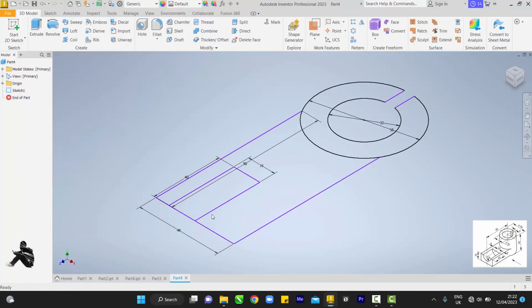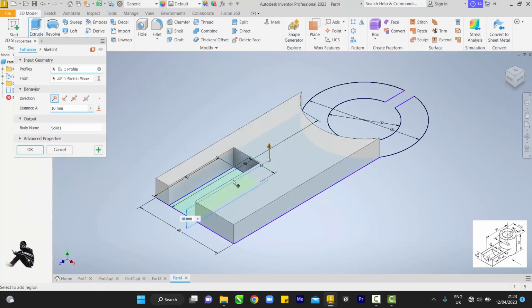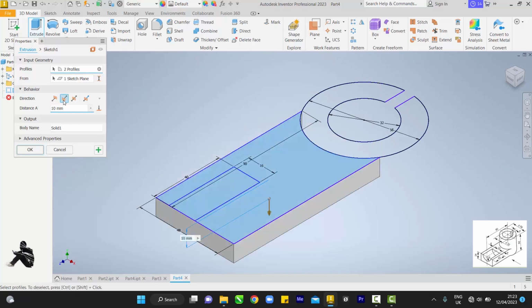Now there are two things to this rectangle I drew here. If I extrude upwards, by the time I revolve, this is going to draw an N, but I need it to draw a U, so I have to extrude this downwards and upwards, which is symmetry or asymmetry. Since it's not equal, it's going to be asymmetry. So I come to extrude, I touch this. Can you see what's happening now? If I go upwards, by the time I revolve this, it's going to write the N. So I'm going to go downwards, and the distance is 24.